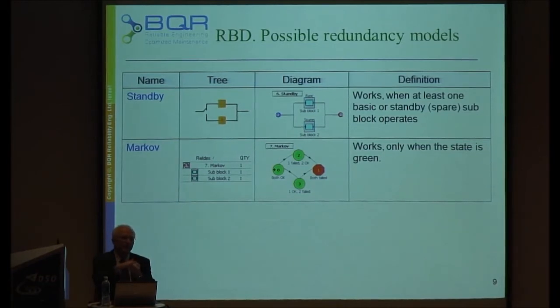And what happened? The metal of the transistor developed something like a needle that goes through the isolation, makes a hole, hitting the ground. So the transistor was short to ground. And now we switched on the TV. There was a spark, and everything there was gone.